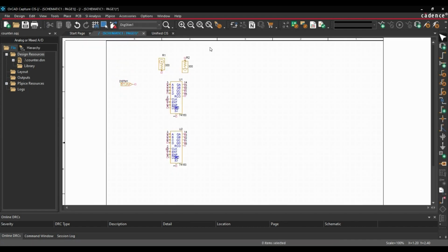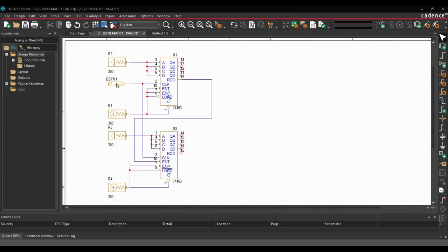Next we are going to make the circuit using these components. I'm going to do that quickly. So as you can see, till now we have created this schematic and we have these pull-ups and pull-downs connected to input of this counter. So this is the 8-bit counter. At every rising edge of clock, this counter will toggle and after 255 counts, it will reset itself, alright, and begin from 0 again. So this is the entire design. It's a very simple 8-bit counter circuit.